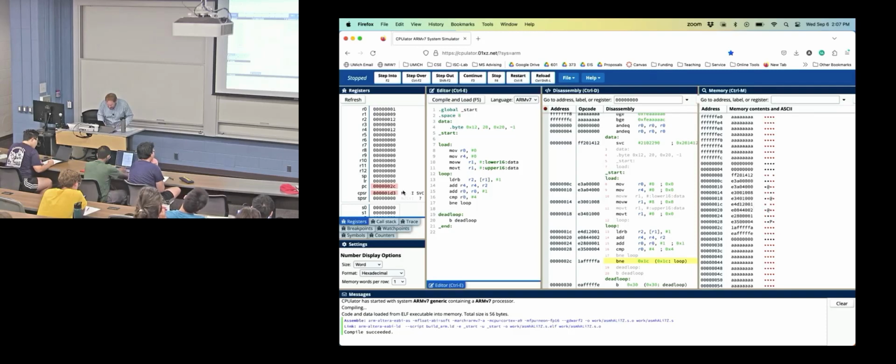In fact, we can see the flag here. This is the program status register. Those are showing you the flags right there. And then we're going to go back through our loop. And the address here, I should have pointed this out, it used to be 8, now it's 9, because when we did our load byte instruction, we did post indexing, which added 1 to the 8, incrementing that value in the register.